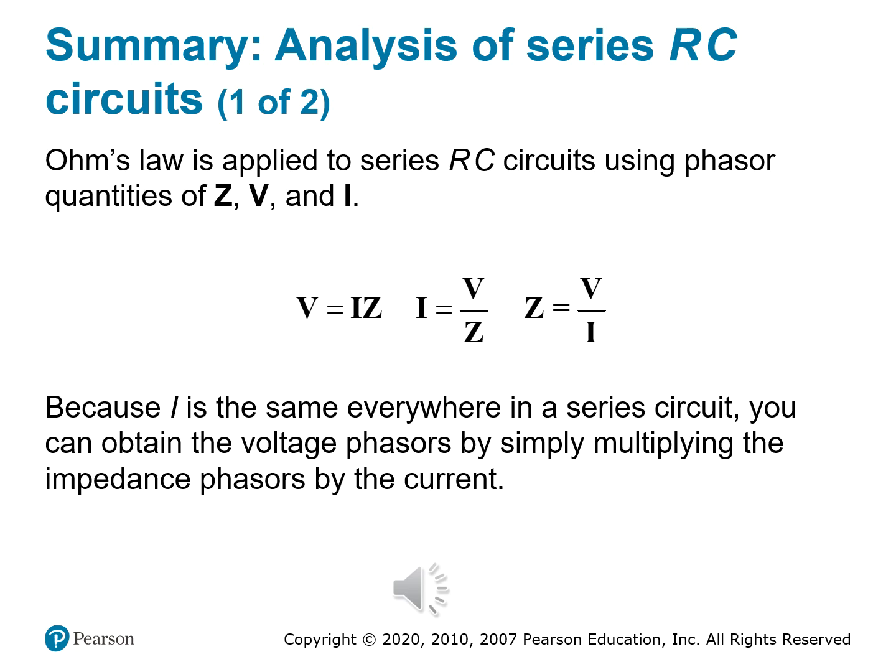So again, remember, when we analyzed those RL circuits, the strategy here is almost identical. The only major change is the direction of the reactance. So inductors, where we had the plus jX sub L, current lags. Capacitors, where we have negative jX sub C, the current leads. The math engine is the same. The only shift is the sign of the reactance and which waveform gets ahead of the other.